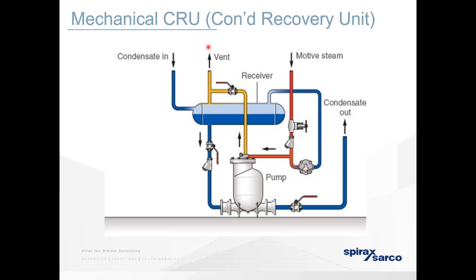But again, there are ways around that. As long as you can purify the steam close to point of use and then use stainless steel piping afterwards, it doesn't mean your entire system needs to be stainless steel. You can reduce costs by making the mains and the distribution to a point mild steel and then changing to a harder material. But just from the point of view of maintenance and the erosion, corrosion, as you said, stainless steel will always be the superior material. Hopefully that answers that question.